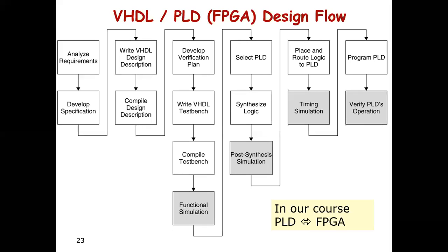First analyze the requirements, then develop the specification, then write the VHDL design description, compile the design description, develop the verification plan, write the VHDL test bench, compile the test bench, then functional simulation, then select the PLD, then synthesize logic, then post synthesis simulation, then place and route logic to the PLD, timing simulation, program the PLD, and verify the PLD's operation. This is the design flow of VHDL or PLD.